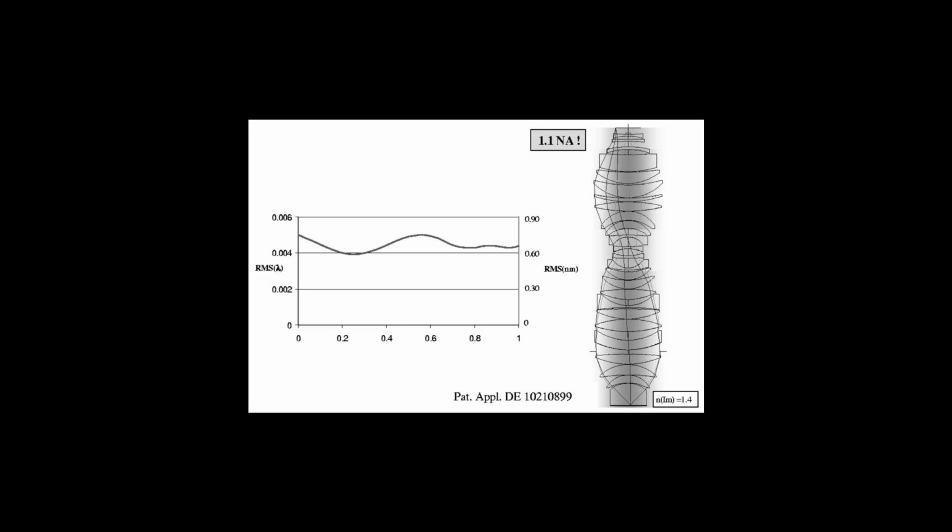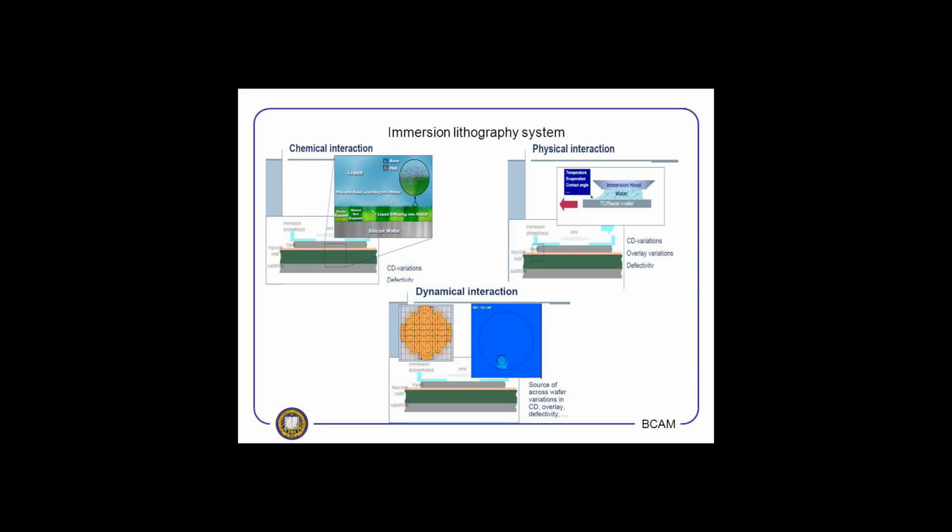On the other hand, double patterning has received interest recently since it can potentially increase the half-pitch resolution by a factor of 2. This could allow the use of immersion lithography tools beyond the 32 nanometers node, potentially to the 16 nanometers node. While double patterning improves pitch resolution, it must rely on non-lithographic methods, such as trimming, to actually reduce the feature size, possibly by as much as 50%.